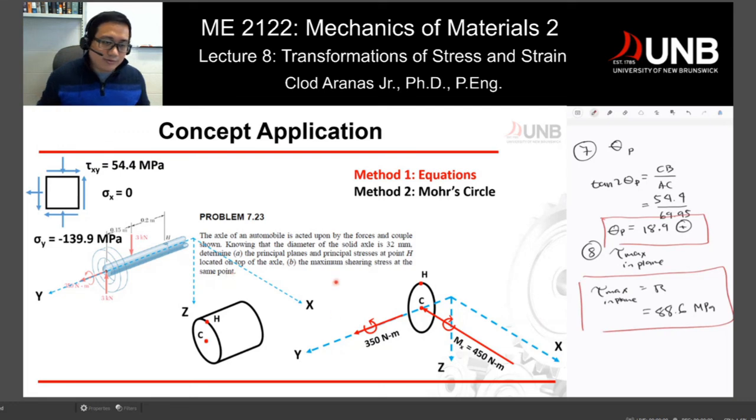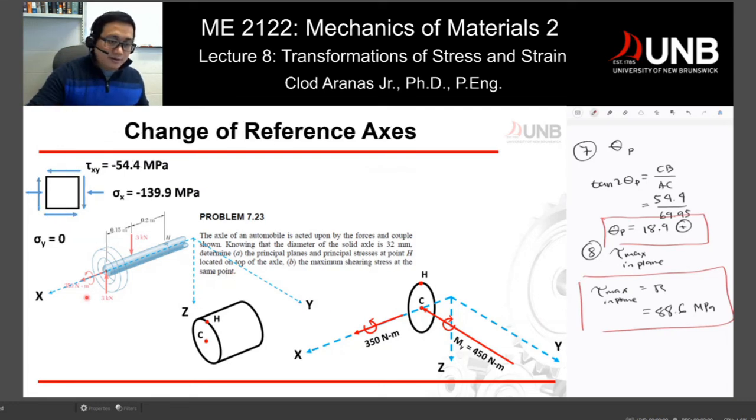But I'm showing you what if I switch my x and y? Again, this is not referring to positive and negative. I'm going to fix that and re-upload this slide. If I put this one as x and this one as y and solve my problem, I'm going to get this stress state here, which now has different values, or at least different directions for my shear and my normal stress. That would lead to a different answer, not entirely different. It's just positive and negative.